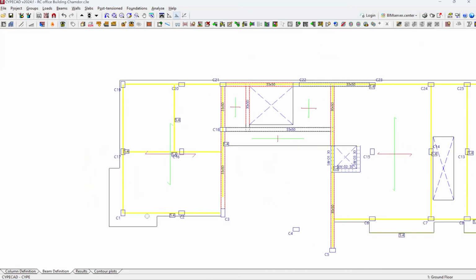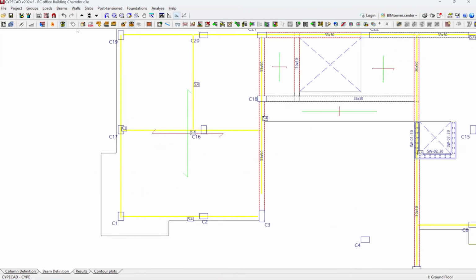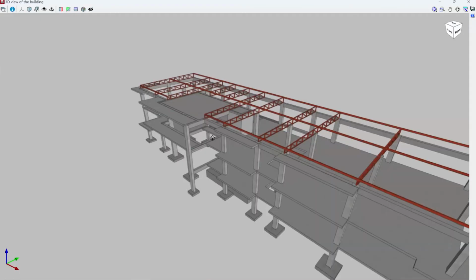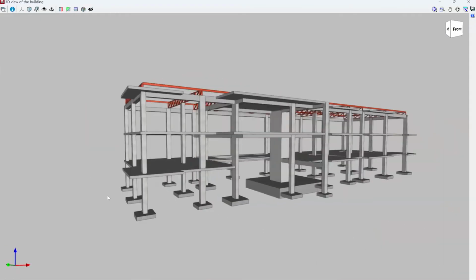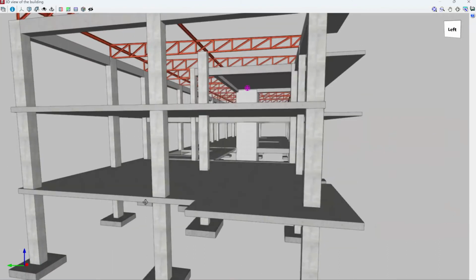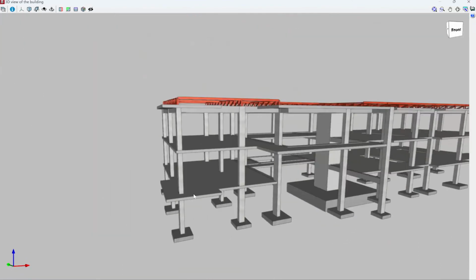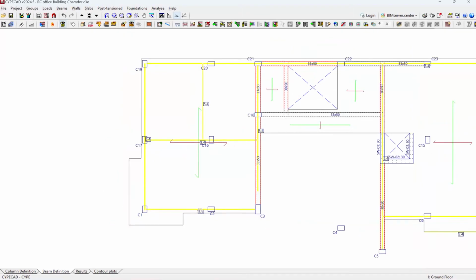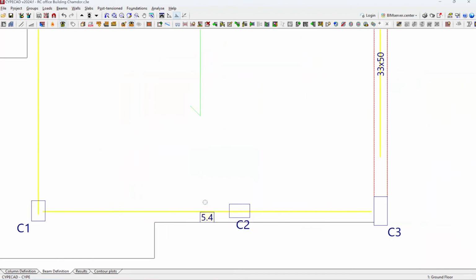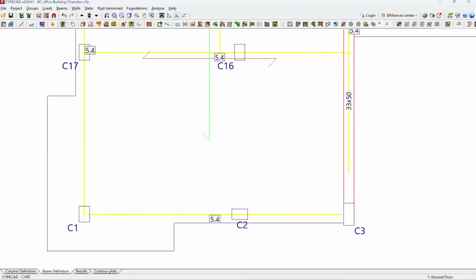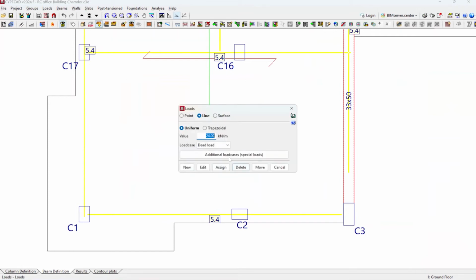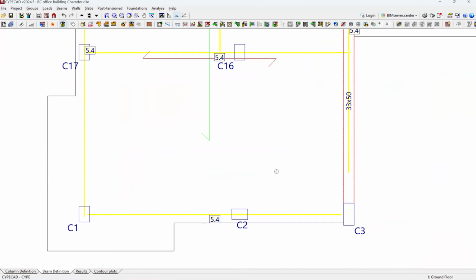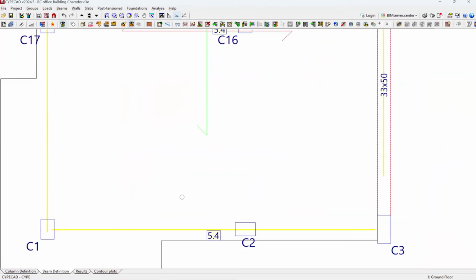And slabs. And also the other thing to consider is that if you're designing this type of structure and you are not assigning any walls, remember, this slab here is going to have walls, for example, from this column to that one. So what we normally do is consider the wall load. In South Africa, most consulting engineers use 5.4 kilonewton per meter for load-bearing walls or twin walls.